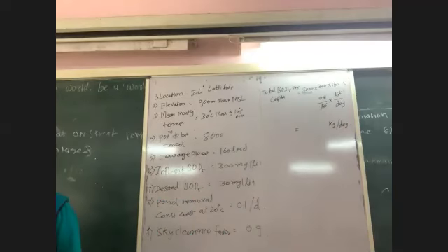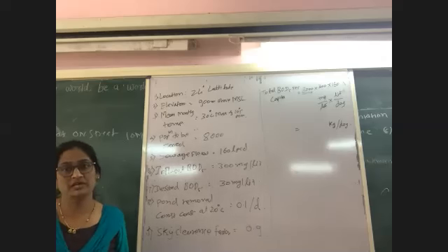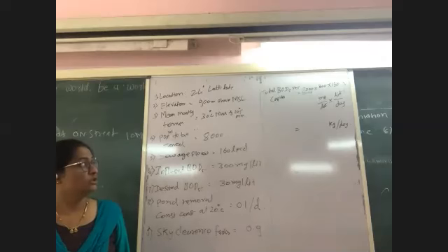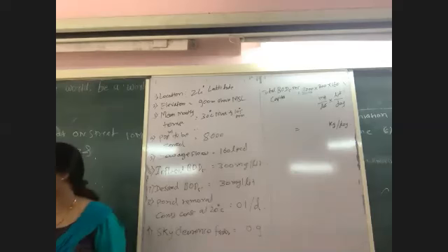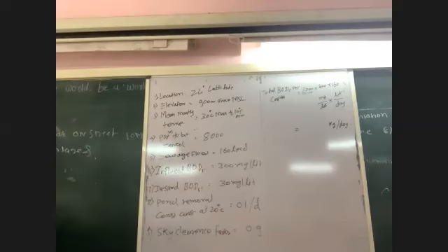8,000 is the population, 160 liter per capita per day is the sewage flow, and 300 is the BOD in the influent sewage in milligram per liter. So unit conversion you need to go for and give me the final answer for the total BOD per day.